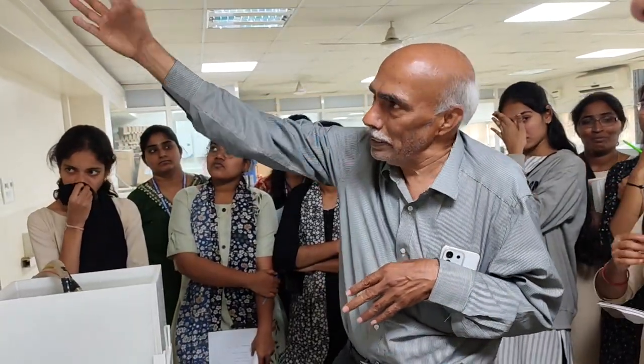The sensors are different types of sensors. One sensor has current output, one sensor has voltage output. Any sensor, you take temperature, flow, pressure, level, it produces only two outputs. One is voltage output or current output. That you should keep in mind. Any sensor, level you are measuring, the output is coming here.